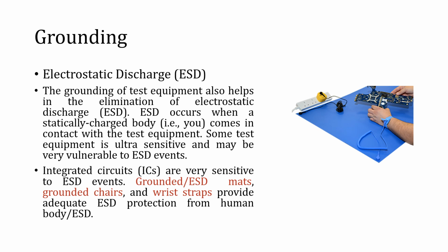If you have come across some kind of sensitive devices or circuits, you must have seen that a few of the devices are wrapped in yellow kind of envelopes, or there is a very large sticker of yellow color, and on that yellow color sticker there is a symbol like this. So that yellow sticker pasted on that envelope means the circuit board inside that envelope is very sensitive to electrostatic discharge. So be careful whenever you are handling those kinds of ICs, batteries, memories, or circuits.